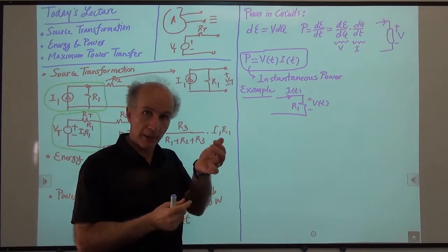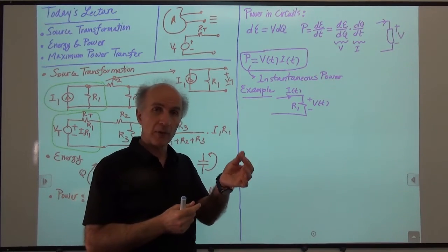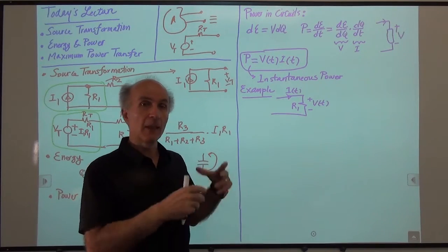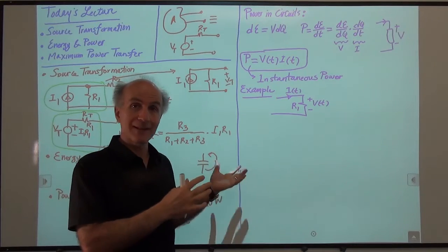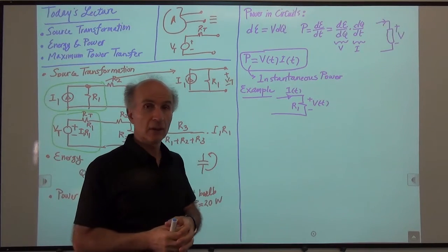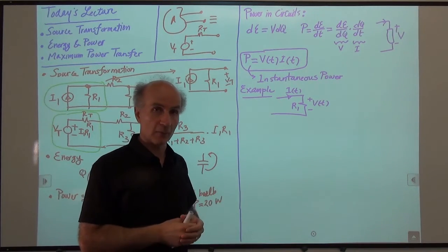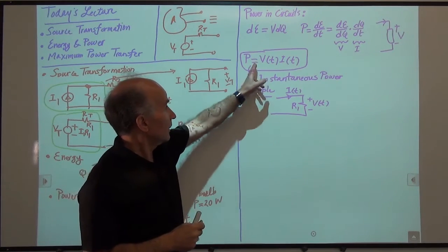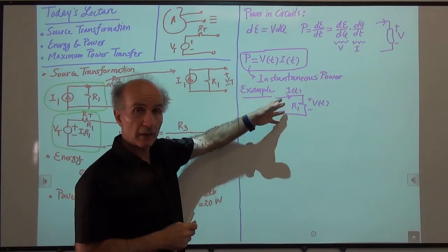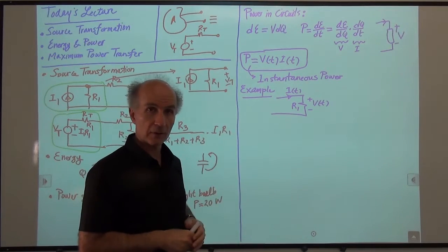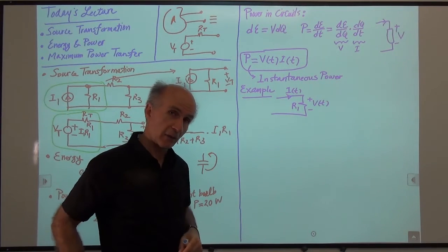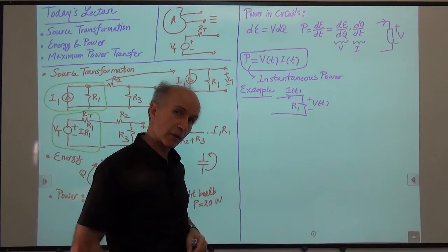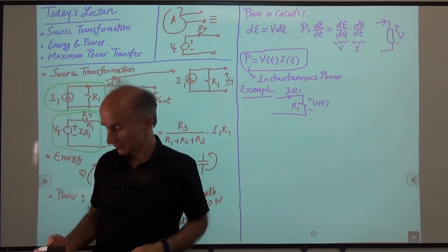Of course, whether we can feel the warmth or not depends on how much it heats up. But in general, a resistor just dissipates the energy in the form of heat. Right? The energy cannot go back to the circuit anymore. All right, so we need to apply this equation to this device to find the power equation for a resistor. That's the quiz of the day. I'll give you 60 seconds to think about it and see what it will look like.